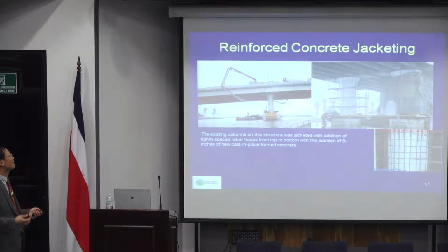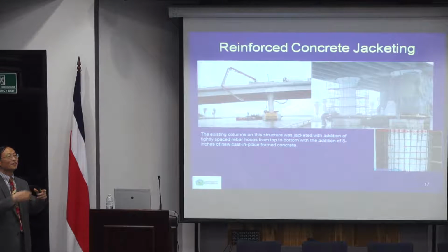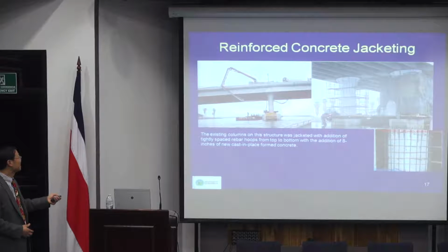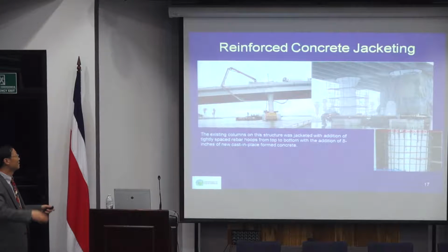Of course, if you do a retrofit like earthquake analysis, you may find that it is just too small. So sometimes, once it's too small, you put a steel jacket or wrap, but that may not increase capacity sufficiently. In that case, you may actually make it larger. Like in this case, they make the column much larger. They basically just put another layer of reinforced concrete.